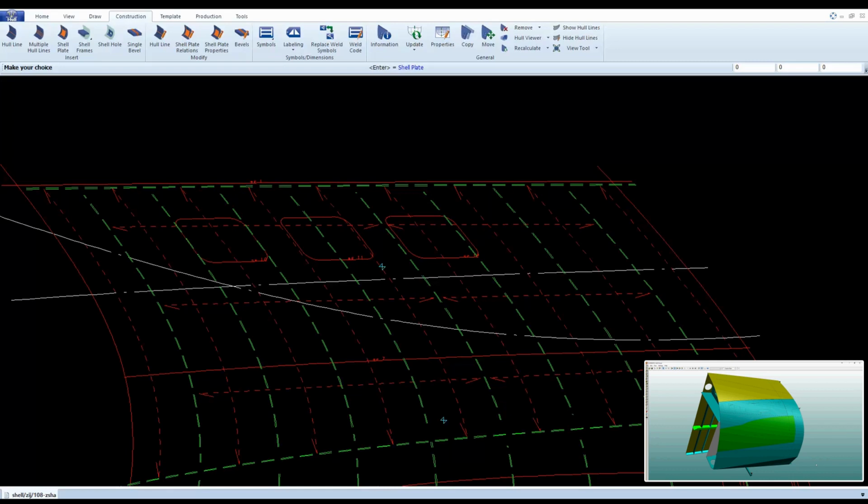In this new system, the algorithm will only use the shape surface to calculate the shell plate. It has the benefit that, as you can see, the plates will get their right form and contour on the shape. The module mathematically calculates even double curved plates into a flat pattern, taking care of the required shrink caused by the double curvature. Due to the accurate computation, shell plates can be developed without extra length.